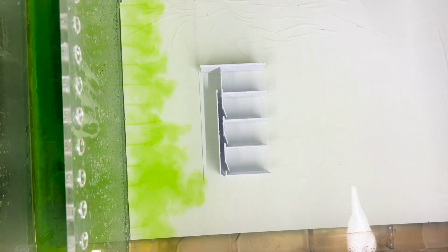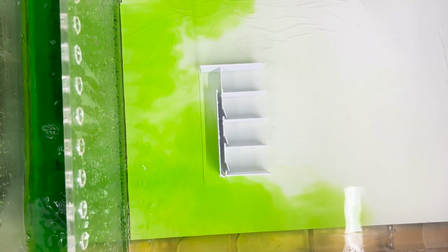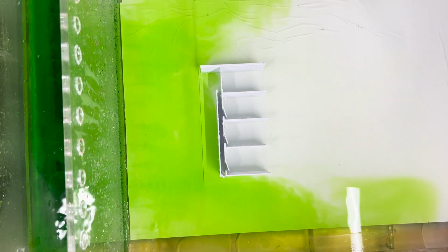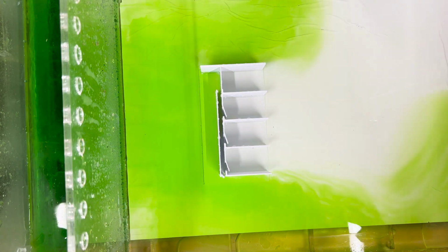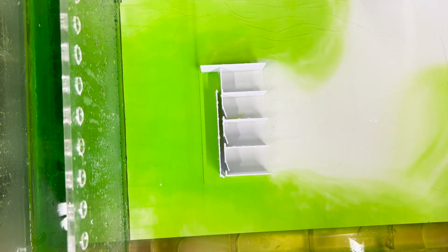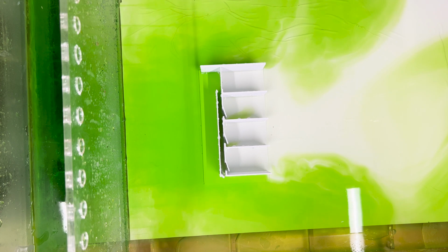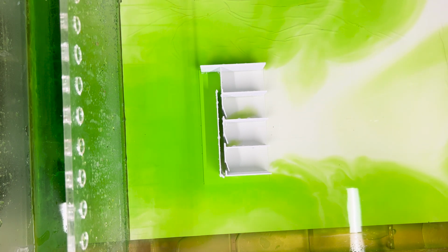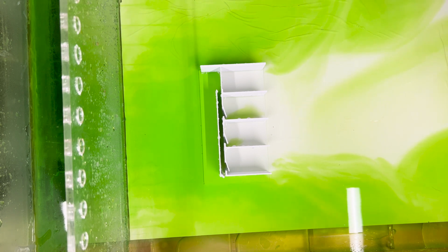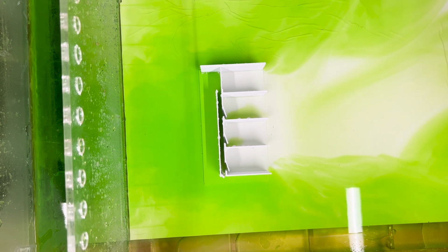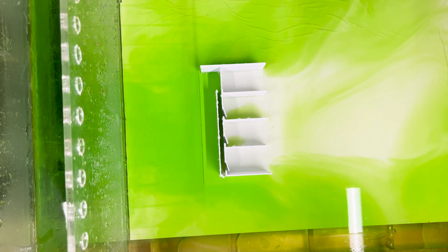Third and final test shows how it can look where these would be open. When testing this, we noticed though that a lot of our openings aren't big enough because of the scale we're working at, and it leads to a limited effect of actual visibility, seeing the stack effect play out. One other factor could be the lack of difference in air temperature, because stack effect plays on the fact that a space would be heated or cooled on the inside, helping aid in this movement of air through this exterior channel and into the space.